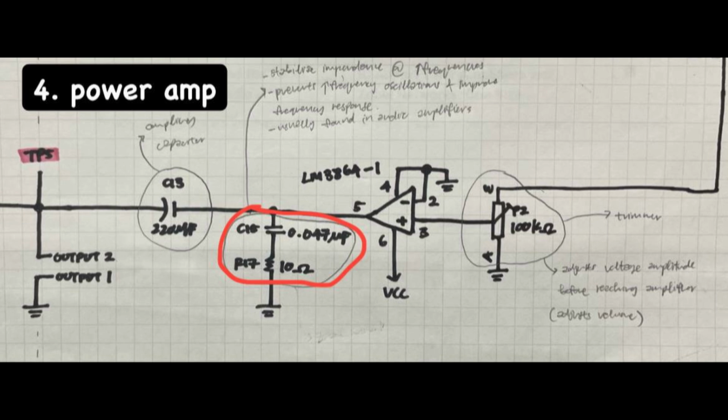This network is connected in parallel to the speaker to minimize the effects of the inductance already present in the speaker. The very last capacitor, C13, is a coupling capacitor blocking off DC signals and allowing AC signals to be amplified at the speaker.